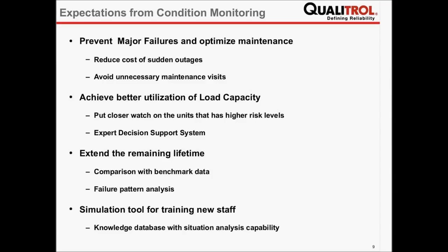Extend the remaining lifetime by comparing the health related parameters of a transformer with the benchmark data from the OEM or with the benchmark data from normal operation, or they want to do failure pattern analysis, and depending on the failure pattern analysis, they want to predict the life of transformers of the same family.